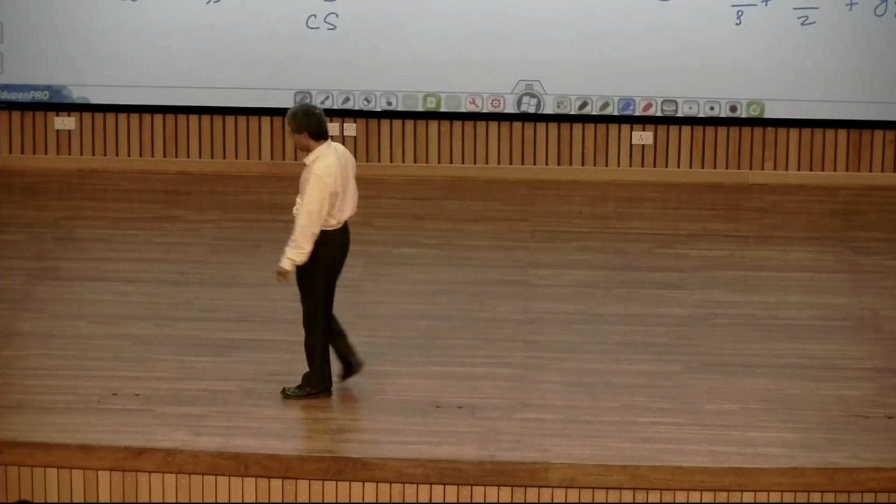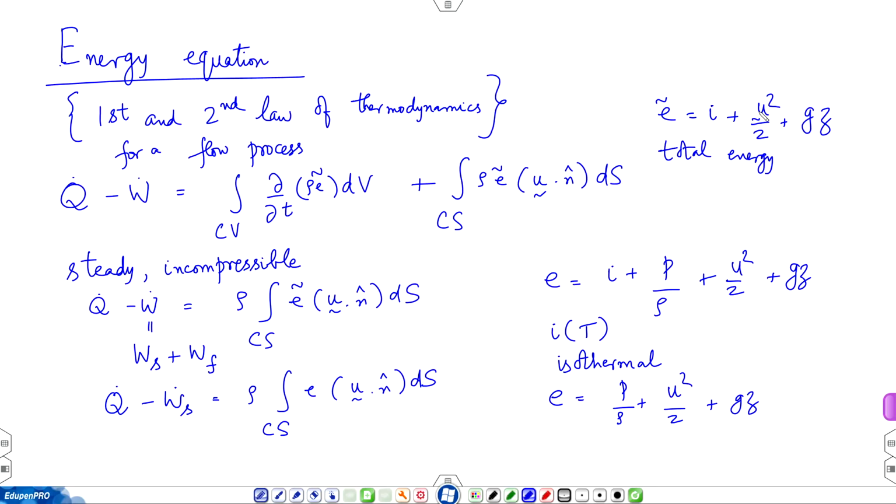Okay. So, if that is the case, then this internal dissipation will get converted into thermal energy of the fluid, and its temperature will try to go up. But if you insist the temperature is constant, then it means you are providing some kind of active cooling to the medium, and the heating effect is being transferred to the environment. So, if the process is isothermal, Q dot has to be from within to the environment.